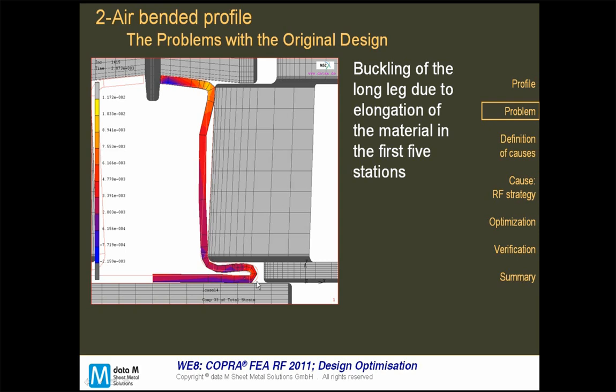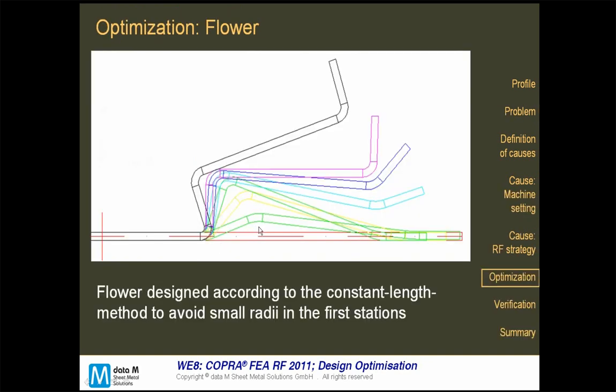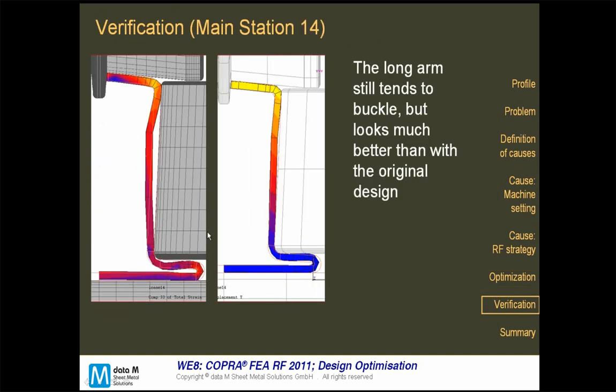to this area. And we could see that the problem was that the necking of this 180-degree bend made the material flow to the inside, which was trapped between two bends. So in this case, again, the calibration method was changed.